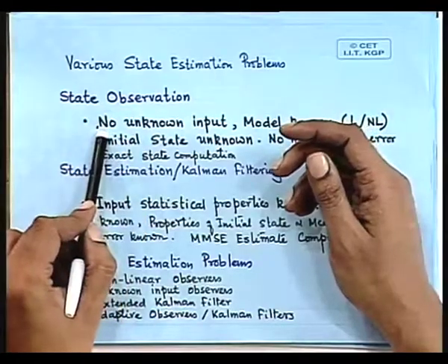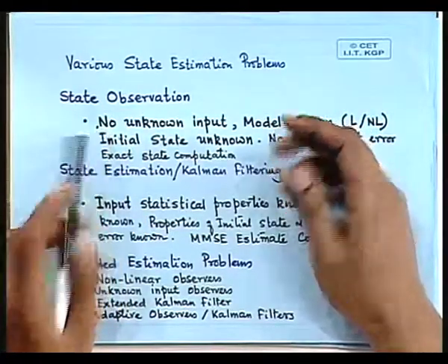The other kind is called disturbance inputs, which are applied by the environment. In general you have no control over them, and often they are unmeasurable. So for this state observation problem, in its simplest form, we are not considering disturbance input. All inputs are assumed known.